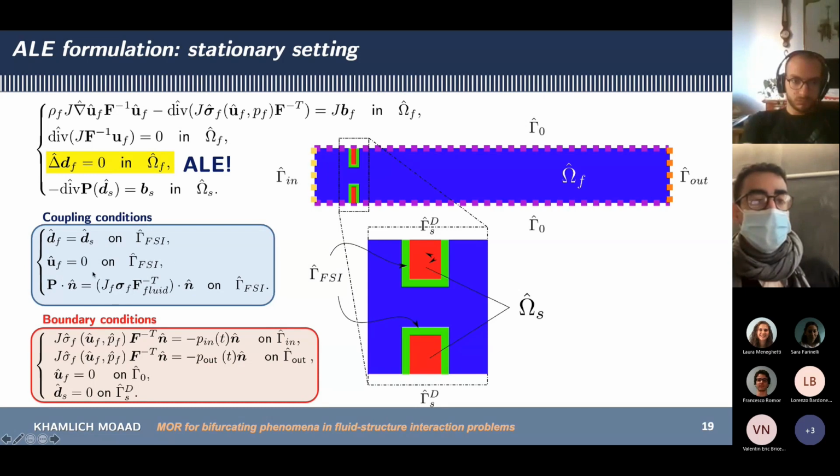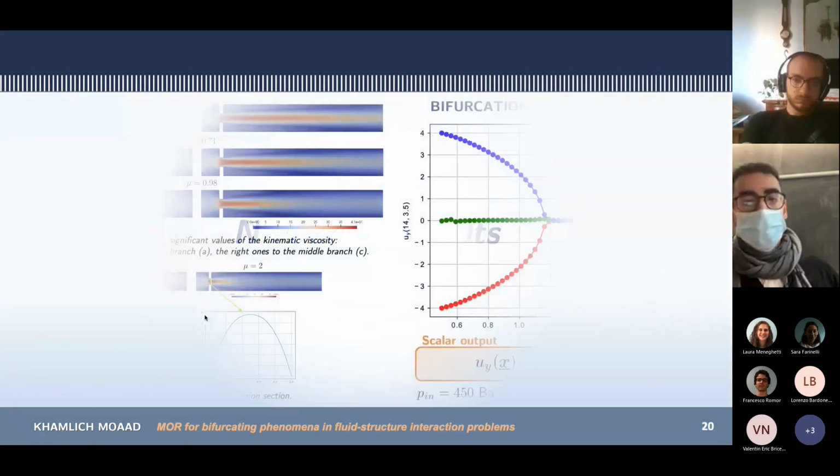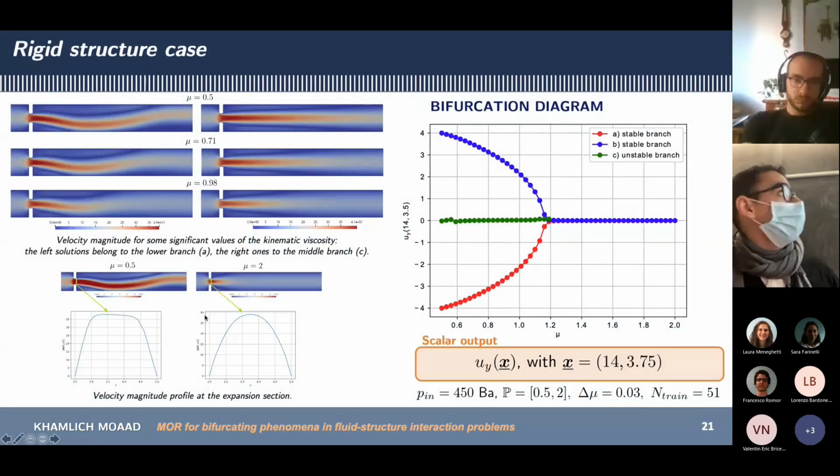And then the last thing will be to introduce also a set of boundary conditions. The one we've chosen was to impose a gradient of stresses between the inlet and the outlet of the channel in order to animate the flow. Then we will obviously have a non-slip boundary condition on the other boundary of the solid on the fluid resolution domain.